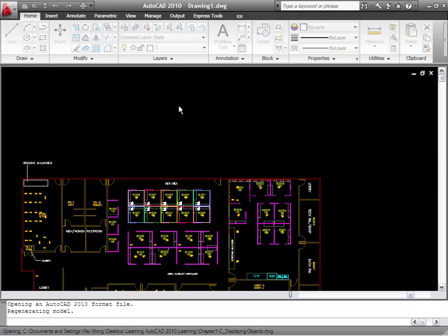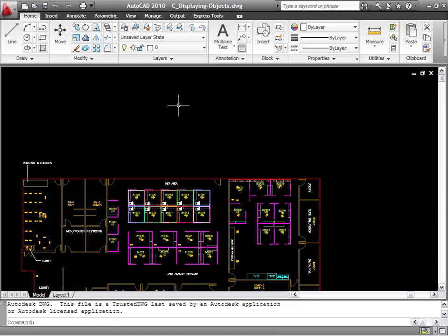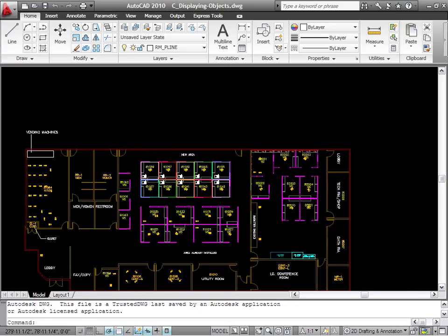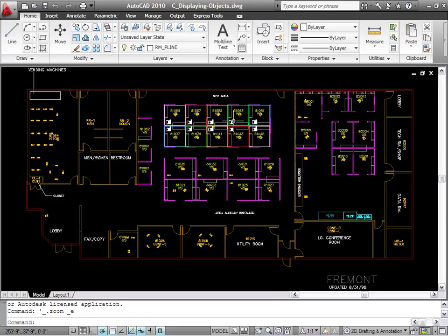So in this drawing, there are circumstances where you have a drawing which is not centralized, which means the drawing that you want to look at is not in the center of the workspace. So in this case, the shortcut command to make the drawing centralized would be to double click the roller mouse. If you double click the roller mouse, the drawing would be centralized, and this is called zoom extend.